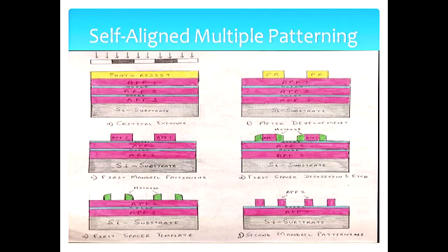You can use any material you like, but again, like I said, choice of material is very important. There has to be etch selectivity between the spacer and the mandrel. In the case of nitride, what etches nitride does not etch the APF, so it is safe to use APF. Again, what etches APF, oxygen, does not etch nitride. So when I etch one, I want the other to remain. That's the reason why I use this.